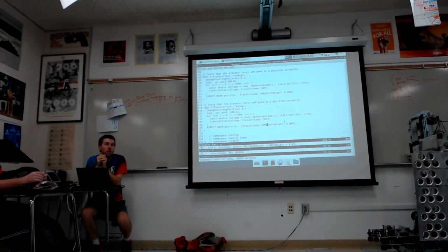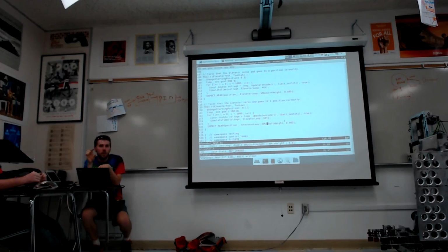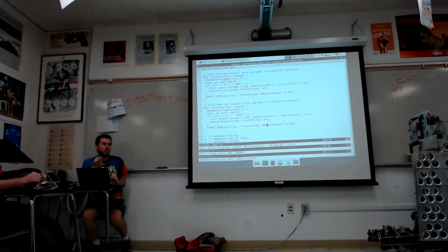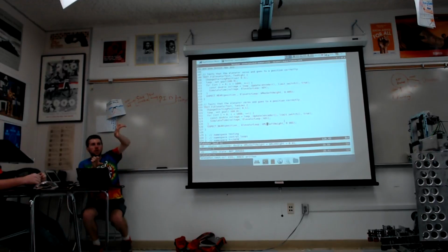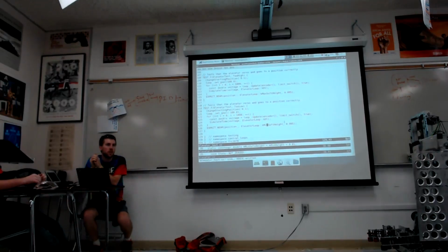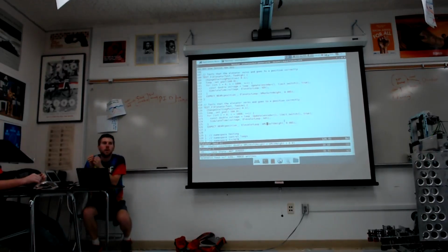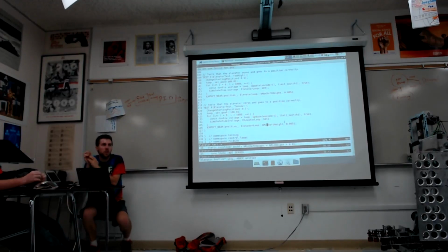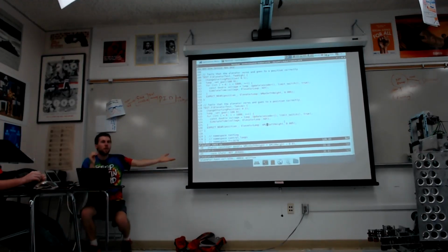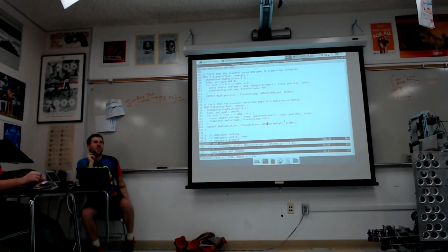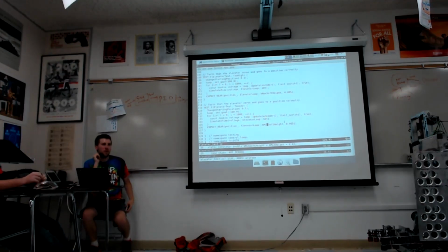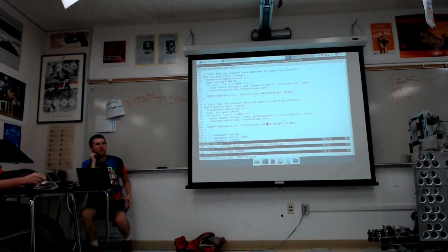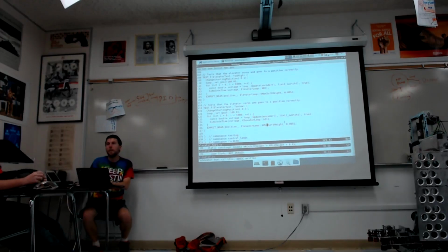On 971 robots, we actually try and design it so the homing sensor is at a place where you can't go past it. So you always know which side you're on, and you can always go towards it. I would probably want to fix this in hardware if we were to do it for real. But this is not my robot, so I can't change the hardware. So we just have to be very careful when we turn the robot on. We're never above the limit. But it's a very good question.